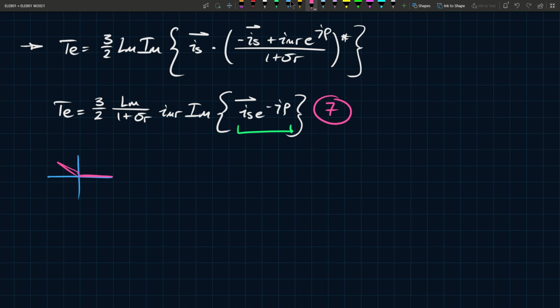you have three signals that are like this, right? So you have phase, let's say A, B, and C. But what we do is you can project these three signals onto a two-dimensional plane that we call alpha and beta. And so this is usually the real and the imaginary component, we can say. But then you can take it one step further, and you can rotate this orthogonal frame, because they call this an orthogonal frame because it's literally orthogonal.